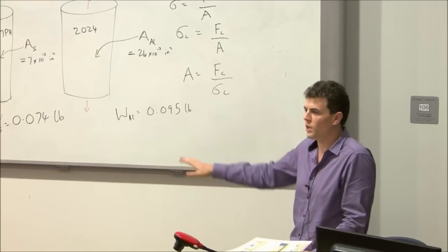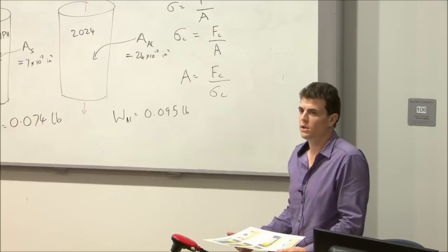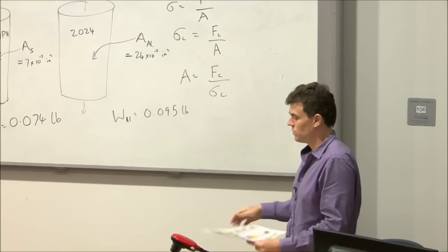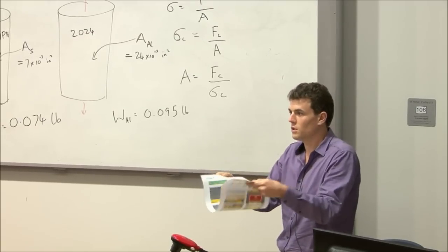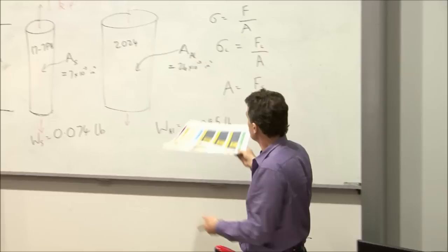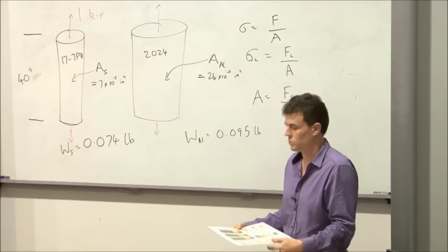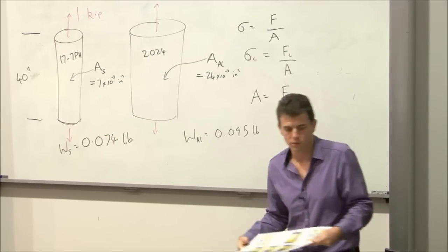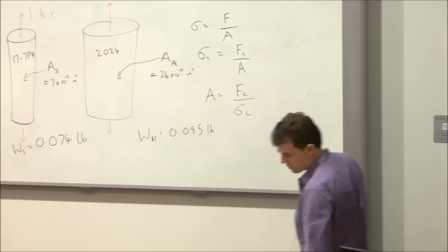When you load a wing up, the top surface is in compression and the bottom surface is in tension. So if we made it out of steel, the top surface of the wings would just do this, okay? Because the steel would be too thin. What happens when we use aluminium is we actually get an increased local bending stiffness, which gives us the ability to take loads in compression. And it's the primary reason that aircraft are built from aluminium.